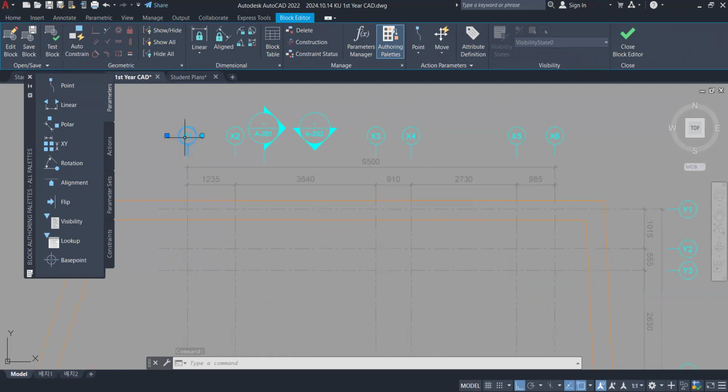You'll notice that they're always facing up. The text is always in a way such that you can read it. So this block is actually created so you can spin the stem very conveniently. This is called a dynamic block, and we'll cover that in a different lecture, but that's how you can use it.